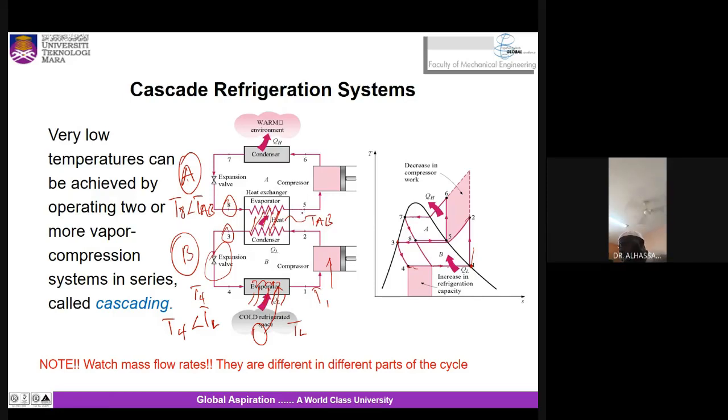So it means the heat will be rejected, and then gradually the fluid will be moving to state 5 at saturated vapor state, before eventually it is compressed again. Okay, slowly it is compressed to superheated state at state 6. Oh, sorry, the heat is rejected, means there is cooling.